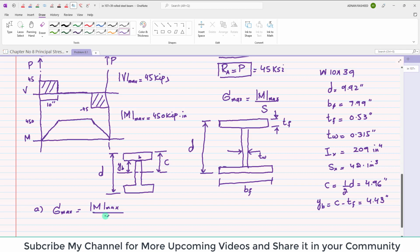Now we know that for part A, maximum stress is equal to maximum bending moment divided by section modulus. We have the maximum bending moment, that is 450 kip-inch. So I will write 450 divided by the section modulus, 42.1 inch cubed. That will give you the maximum stress for the beam, which is 10.69 ksi. This is the stress at the top of the flange, or you can say at the bottom of the flange. So this is the maximum bending stress.